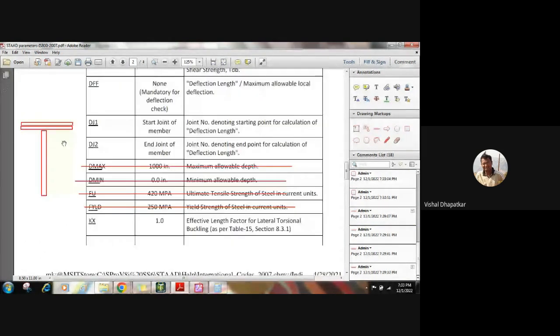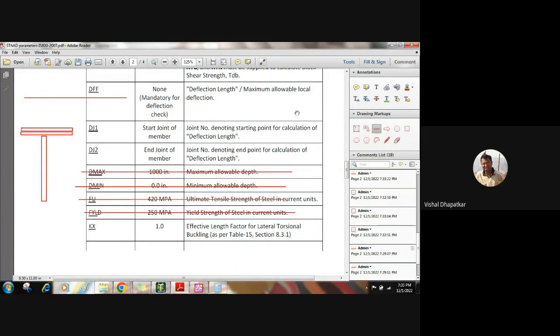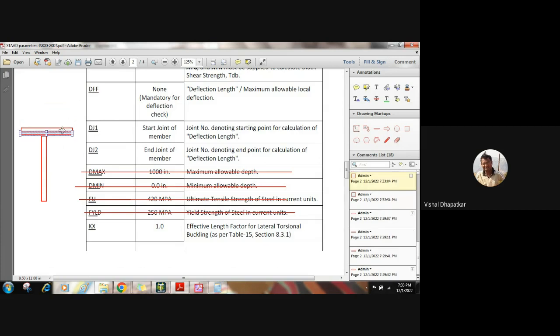First thing, it will provide you the ductility. Second thing, it will give you a chance to make it an optimized section just by reducing the plate thickness, because when we are designing any plate girder, we require the maximum thickness at the center. So you can provide an additional plate for the particular location, and for the rest of the portion you can reduce the thickness of the plate. So this is the advantage of using small plates, and it will also provide you more ductility.